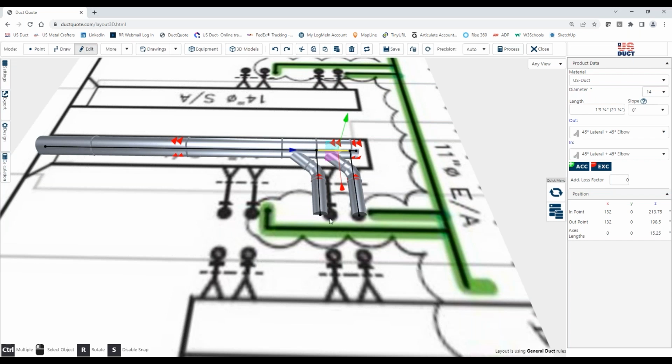Now, if this were a flange connection here, you could do something as simple as having a flange adapter to a hose connection style, and then the flex hose could connect there. Okay, but you've got to talk this through with your client so that they understand and you understand the limitations of and the advantages of using standard versus, say, a custom part. All right, so that's kind of example one. Is we can only fit these branches just so close together, and that is based on the sizes of these entrances and exits.